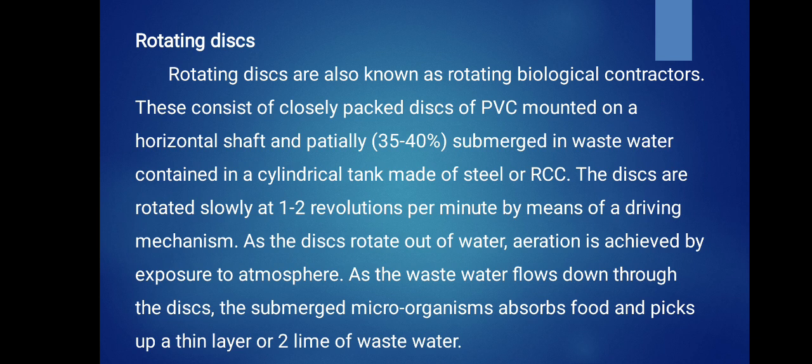When the discs start rotating, then the aeration is achieved by the exposure to atmosphere, because the wastewater treatment must be done in an open surface, open space only, then only we obtain a proper aeration from the atmosphere. As the wastewater flows down through the disc, the submerged microorganisms absorb food and pick up a thin layer of wastewater.